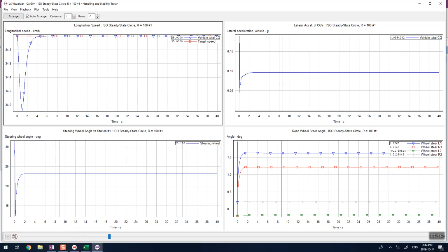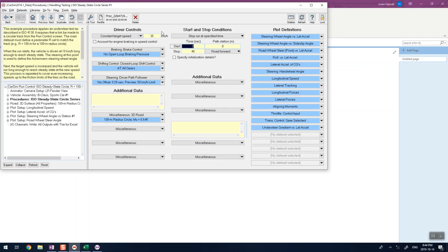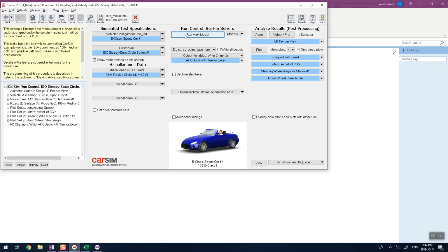The driver should steer more. The lateral acceleration is getting quite a bit higher, at least. It was 0.007 and now 0.009. Steering angles. Go for something higher. What I recommend, we did 10, 35. You do 50. You do 70. And you do 90. I will just run 90 for now for you. And let's run it.